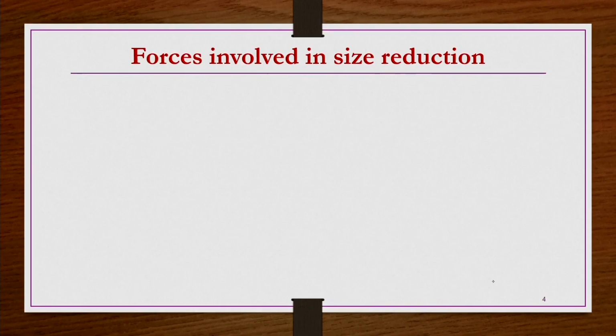Then, what are the forces involved in size reduction? We realize the importance of size reduction, especially in solid operations or solid-fluid operations, having seen several applications and examples. But we need to know what forces are required, or involved, in size reduction. Let us say you have a very big rock and you want to get a very fine particle. If you are doing some kind of rubbing or attrition, you may not get that required product.